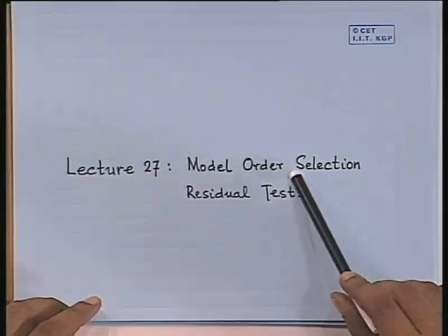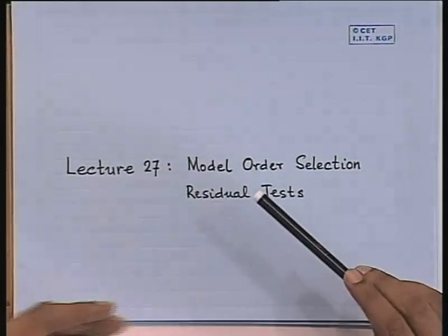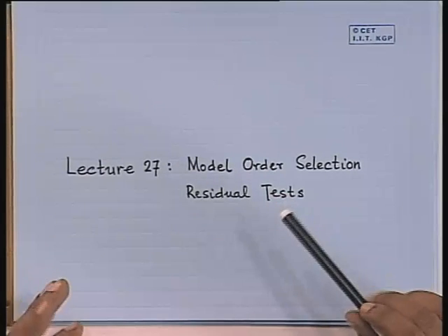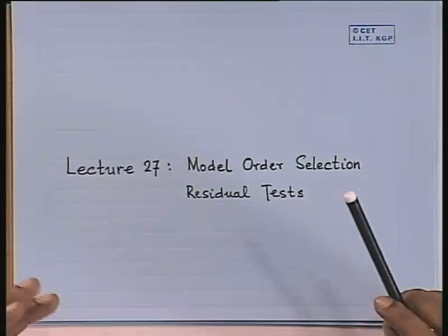I am not saying model order determination, because it's not that you can nicely solve out that the model order is going to be 2. Rather, you have to select whether selection of a model order of 2 serves your purpose well, or selection of 3 is required, or maybe selection of 1 is sufficient. So in general, we would go by the simplest one that works for our purpose. So it's more of a question of what works good enough for my purpose.